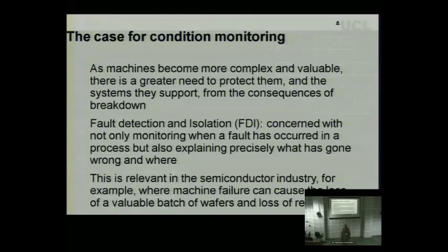So I think the nominal parameters for an observer are less important than for a controller. For a controller, the nominal parameters impact on the performance of the plant. For an observer, the parameters you assume have no impact on the plant at all. It only impacts on the observer. And so long as you get y minus y hat equals 0, you have reasonable performance from your observer, it doesn't need to be exact. You start from a point that is good enough, and you're interested in change.